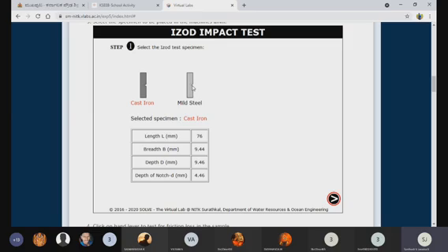We need to take exactly 2 mm, using the hacksaw blade to start cutting; this depth will be 2 mm. Hope you understand. The total length of the sample will be 75, and to make the groove we measure 25 mm from the end.